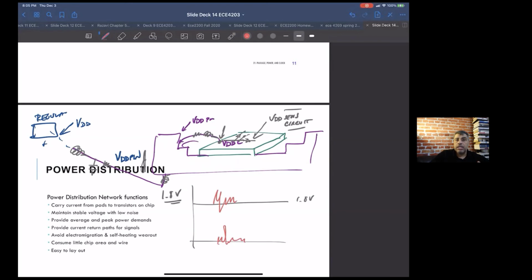The only reason anything works on digital chips is because of the noise margins we were talking about. So those are extremely important, because by the time you're really using these parts in a real system, you're going to have a very, very dirty power supply and a very, very dirty ground.